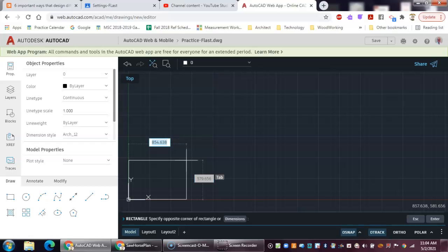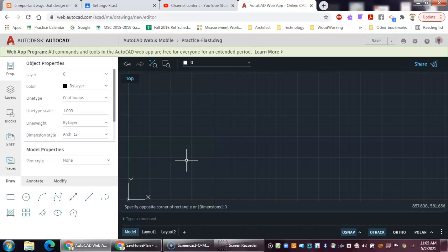So I'm going to physically make the base of the rectangle. I want this to be 2 inches. So I'm going to press the number 2 key, and then I'm going to have a height of 3. Now when I do this, it's going to look like it's real narrow. So tab over, see how it looks like it's real narrow now. Now I'm going to type in 3, and now it's going to get real small, and I just hit the enter key because I've made both of those.